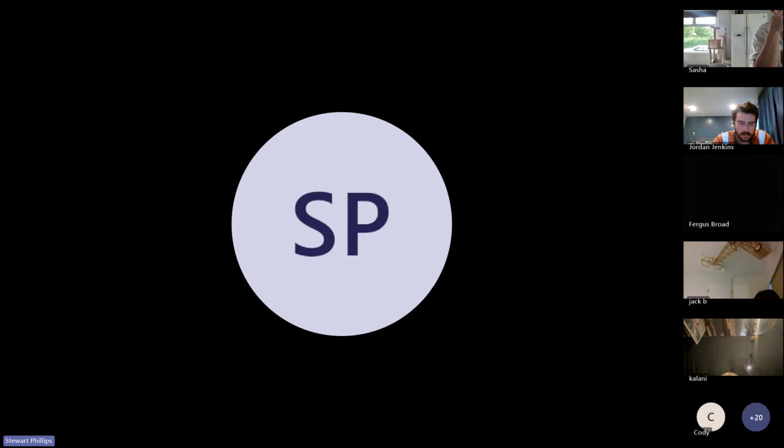Yeah, so mostly we do paperwork for a paper trail, just to confirm we've done things. So when we test an installation that we've done, we make sure we test every circuit. We test pretty much every power point we can. We test every exposed metal part that's bonded because we want to make sure everything is tested properly. And then we need the document to say, hey, we tested everything. When we finished the job, everything was working. And so if something's wrong now, someone else did something dumb.